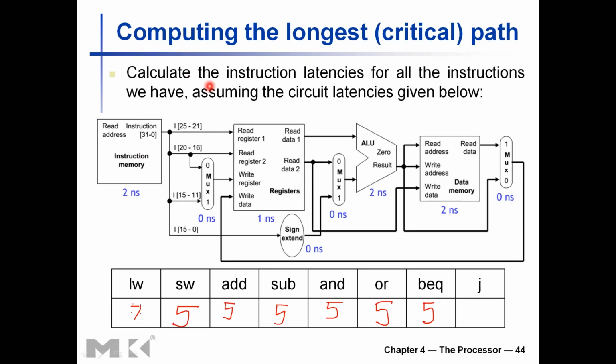From there onwards, it's just about taking the PC plus 4 value, right? That adder, PC plus 4, and getting this 26-bit immediate offset value and appending it to the top 4 bits of the PC plus 4 value with a shift to left operation.